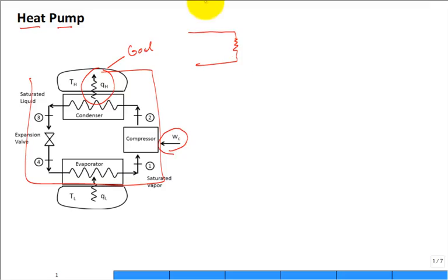But if you put in, let's say, a kilojoule of electricity, work, or energy input, how much heat would you get into the air to then heat your home? 1 kilojoule. Can you do better than that? Sure, if you have a heat pump. So in the heat pump, maybe you put in 1 kilojoule of energy, and maybe you get 3 kilojoules of heat delivered into the house.